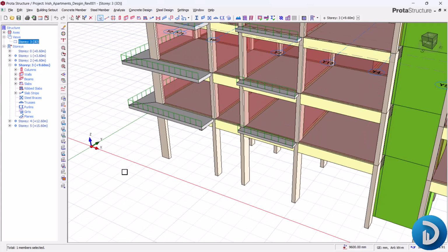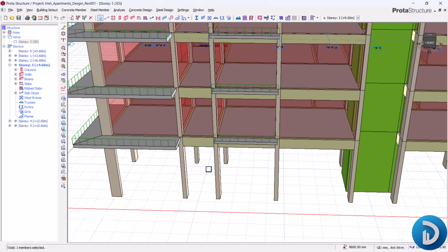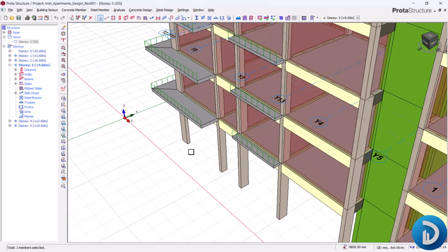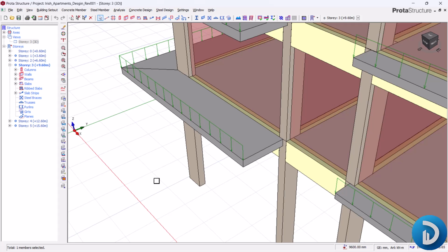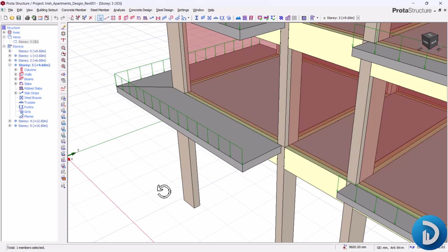And if you are familiar with structural arrangements like this, considering the fact that this is a 1.2 meter cantilever slab with a thickness of 200 millimeters, with these properties, when load is applied on this slab, it will cause a twisting effect on this supporting beam. Okay, it will cause a twisting effect on this supporting beam when load is applied on this slab, thereby generating a torsional moment on our beams.